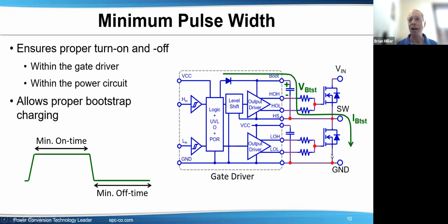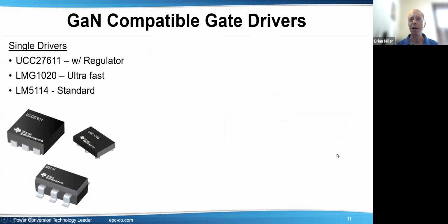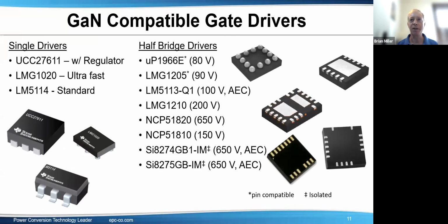That's not ideal for the gate loop in several ways, but the on-semi drivers have another connection, so the bottom gate drive can float up to plus or minus, I think, 3 volts. And that can really help to have both a source connected current sense resistor and good, optimum gate drive.